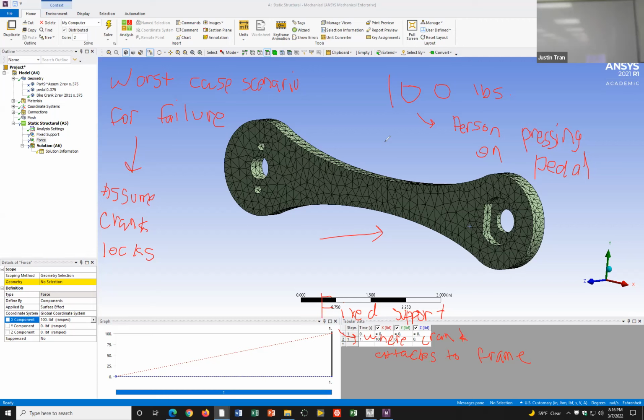And in a lot of the solutions, they just cut it in half. You can do symmetry too. If it's symmetrical, you only have to do half of it. Then instead of doing 4 elements, you just do 2, and you cut the load in half as well, to 40. So then I would just have F1, F2, F2, F3.